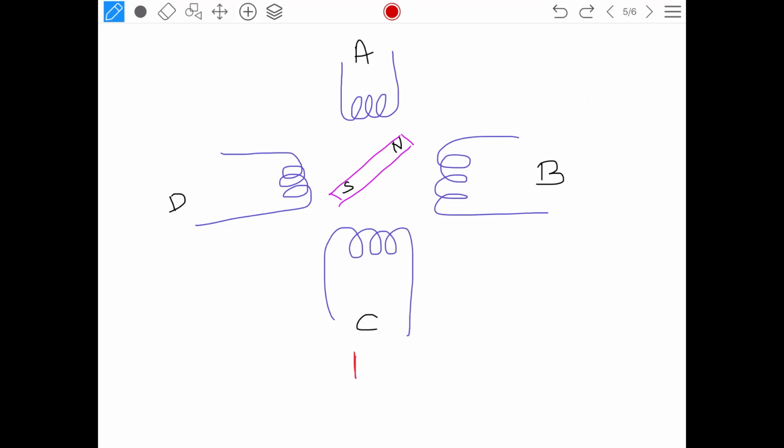Next, I will energize coil B, establishing a north pole, so the sequence will be 0, 1, 0, 0. Lastly, I will energize coil A, so the sequence will be 1, 0, 0, 0. You can see I am shifting the energy in this direction, which is nothing but anticlockwise, or counterclockwise, direction.